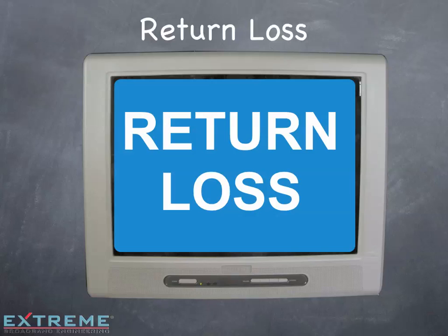Let's look at some of the signal impairments that return loss can cause. With analog video signal, you'll notice ghosting around images. With digital video, you can see freezing or tiling of the picture. And with data, you may experience slow data rates.